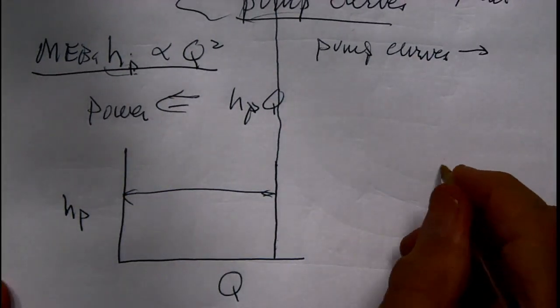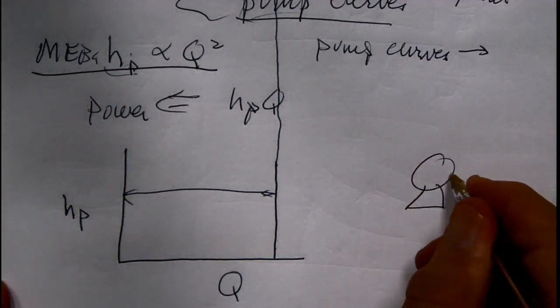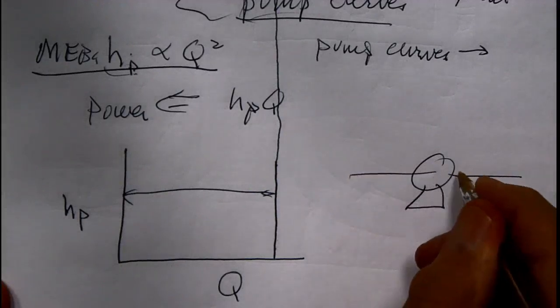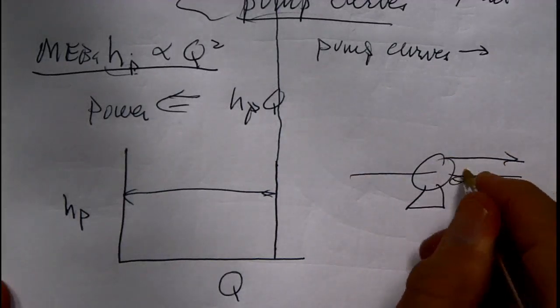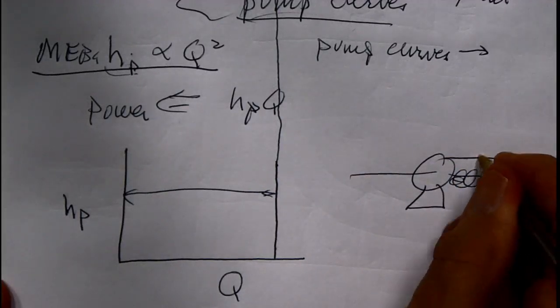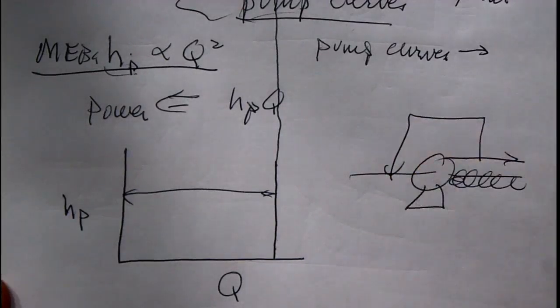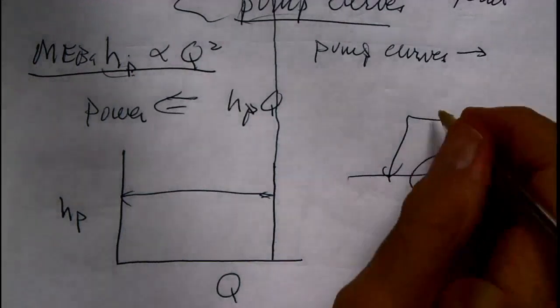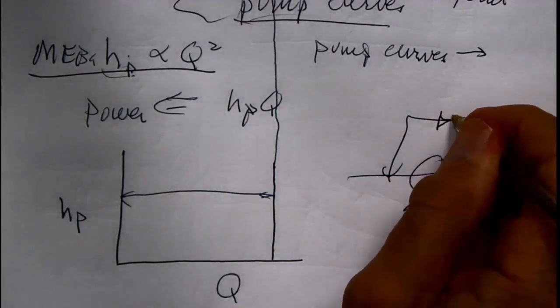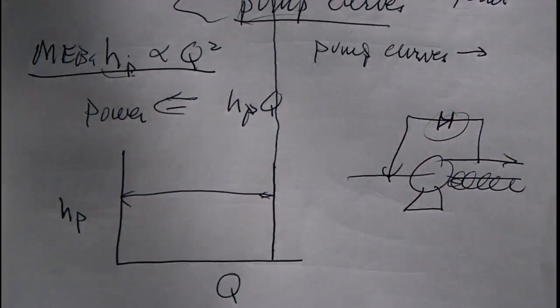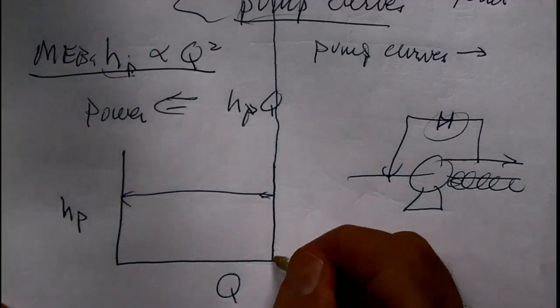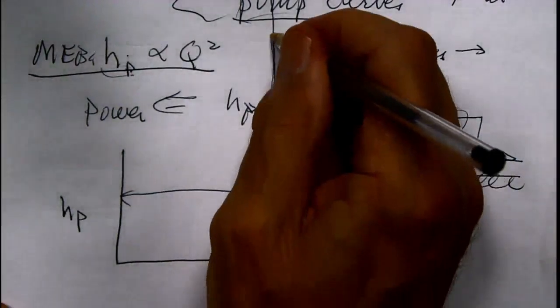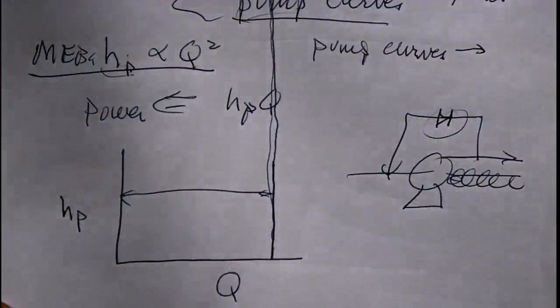So the piping system is you'd have your pump sitting there, the pump exit up here, and you would have a pump-around loop. You always have some sort of flow rate, and the pressure relief would be up here. In positive displacement pumps, you don't want this curve to go on and on and just go up.